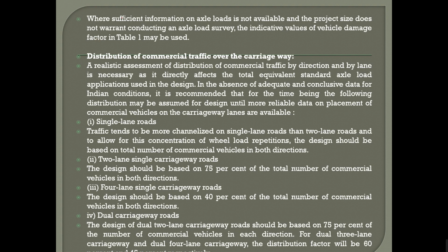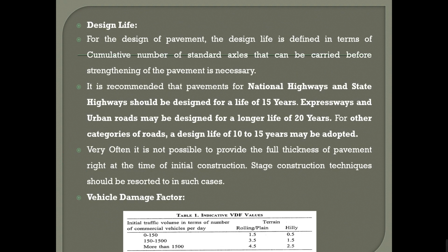Now, wherever the VDF values are not available, when the project size happens to be very large, where sufficient information on the axle load is not available, it does not warrant conducting an axle load survey. So the indicative values of vehicle damaging factors given in Table 1 can be used wherever you cannot conduct the axle load survey. Thereby you are going to make use of this indicative VDF value as per the Indian Roads Congress, as well as if the project size happens to be larger.